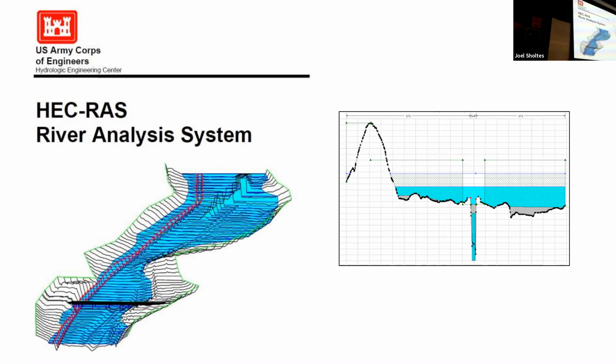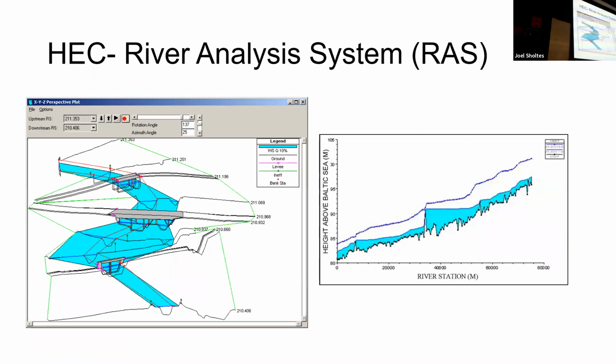Of course, for a given elevation of water, you can get different depths at this cross-section. So there's some two-dimensional information there, but the calculation itself is a one-dimensional calculation. And so each cross-section basically just represents a point. There's one water surface elevation.